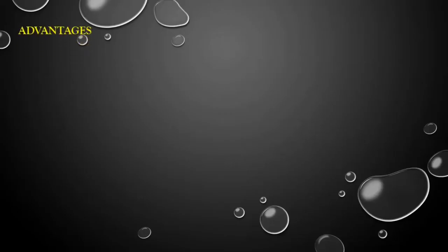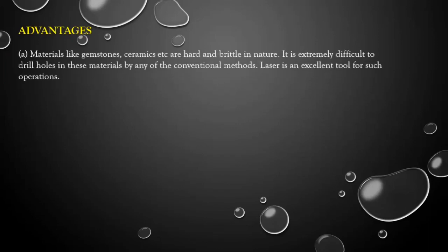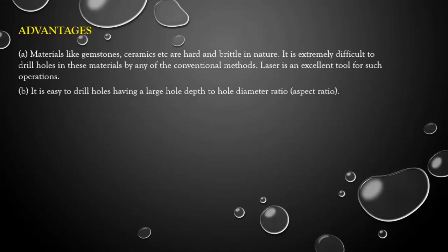Then we move on to the advantages of the drilling process. Materials like gemstones and ceramics are hard and brittle in nature. It is extremely difficult to drill in these materials by any conventional method. Laser is an excellent tool for such operations. It is easy to drill holes having a large hole depth to hole diameter ratio.